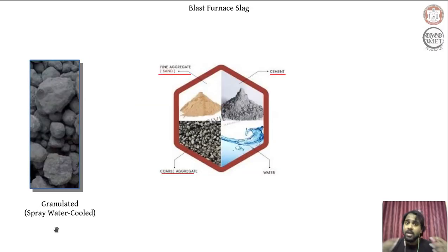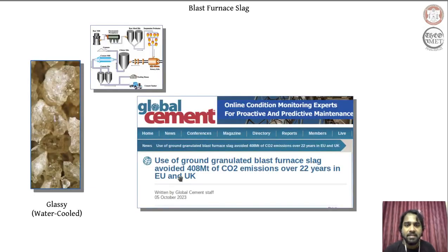And if I want to wind this up, regarding the application or management of the blast furnace slag, we have to consider the final form of the blast furnace slag, that is the granulated blast furnace slag. As you can see here, this granulated blast furnace slag can be used to replace almost all components of the concrete, except for the water. So that is exactly what you see here. Even in minimizing the amount of CO2 released, we can use this granulated blast furnace slag.